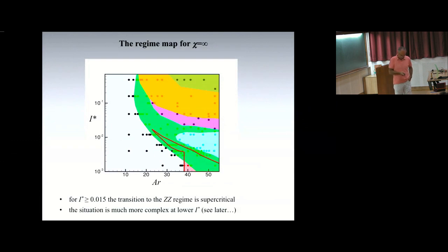And so now, here are the results. So the results, actually, you may summarize them into this phase diagram. So this is for an infinitely thin disk, which is the one I am going to comment on first. So this is the phase diagram we obtained. So again, the Archimedes number and the disk inertia ratio, okay? So the gray region is the one in which the disk just falls or rises broadside on, and all the colored regions correspond to different non-vertical states, on which I'm going to comment now.